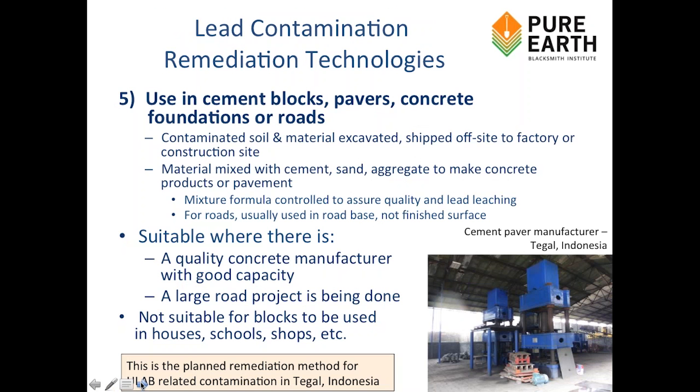The 5th technology is use in cement blocks, pavers, or concrete foundations, or using contaminated material in roads. The formula that you use for the mixture has to be tested and properly designed. You don't want the lead to leach out of the concrete that you're creating. This is a suitable technology where you've got a good quality concrete manufacturer nearby, or where you have large projects.